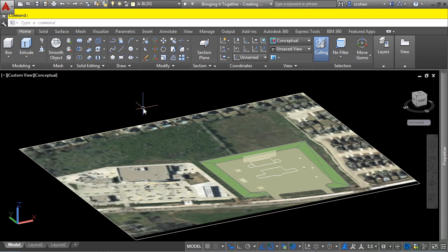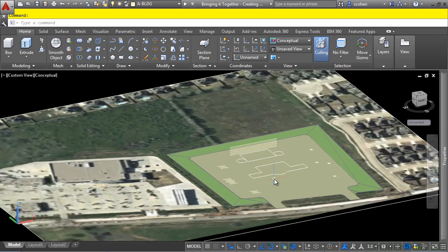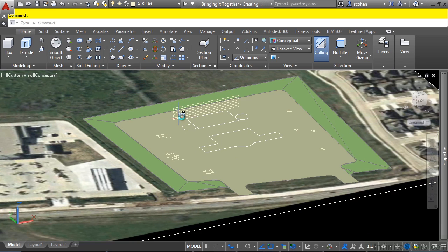Let's bring it all together in a real-world example of performing some mass modeling of a conceptual design of our office park. We'll be creating solids using the press pull command, some extrusions, as well as the subtraction command. If you look in our file, you'll notice some existing 2D geometry that we will use as 2D profiles. Before we begin, let's check our settings.